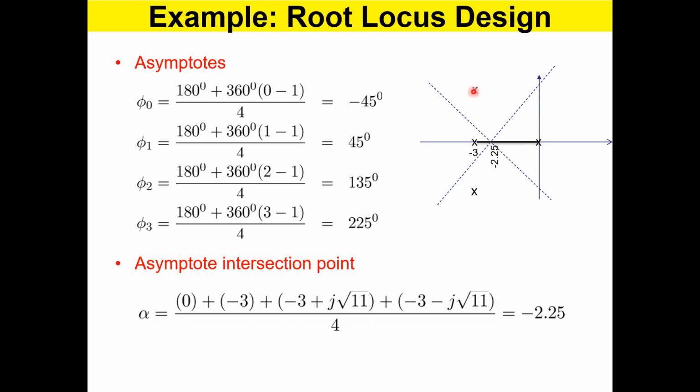What about these two poles, this one and this one? When I start increasing K, what is the heading direction of this pole? Whether it goes up, down, left, right, or any other direction. So that is what is called angle of departure. You have to calculate the angle of departure for one of these poles. Then the other one would be the mirror image.